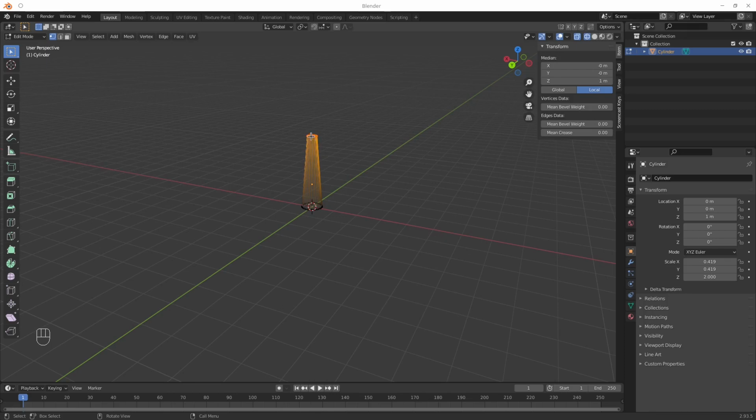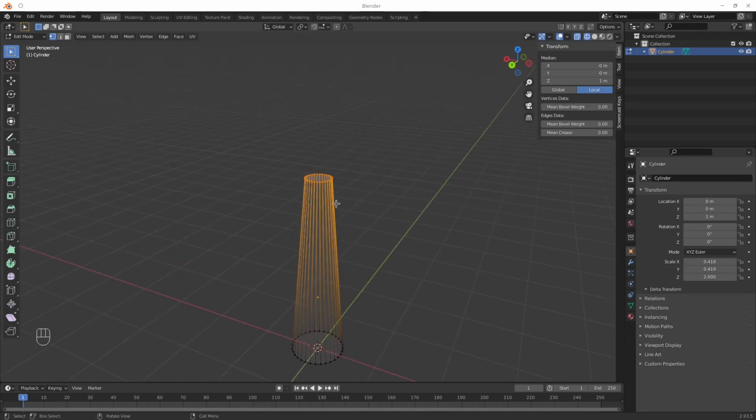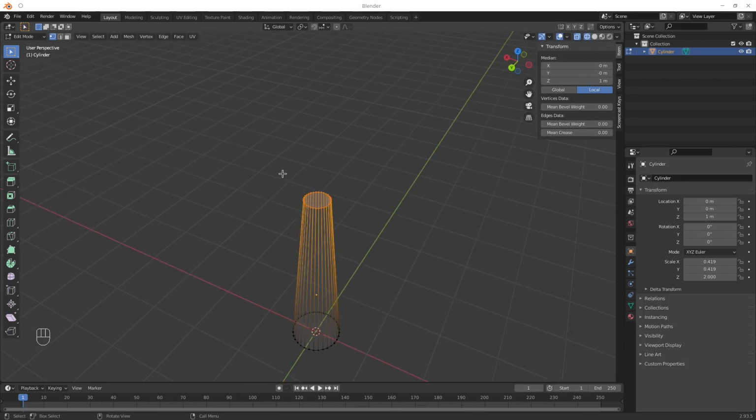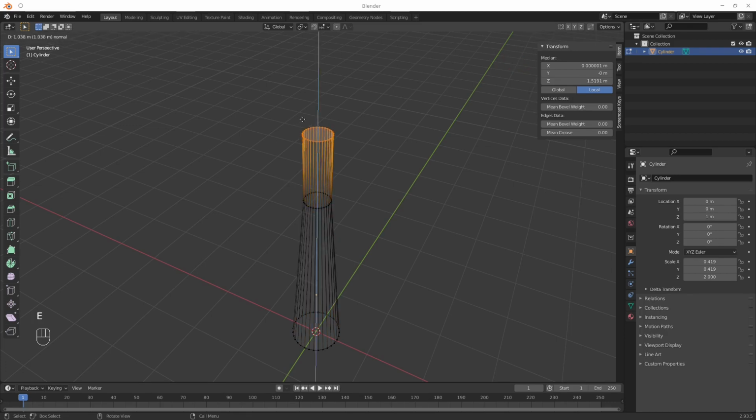If you want to extrude this up and not just move it, you want to extrude that area, you select that face or the vertices around it and press E for extrude. And that will extrude in the most logical direction, but you can also lock it if you want that. So like that. Let me scale that down a bit, like that.